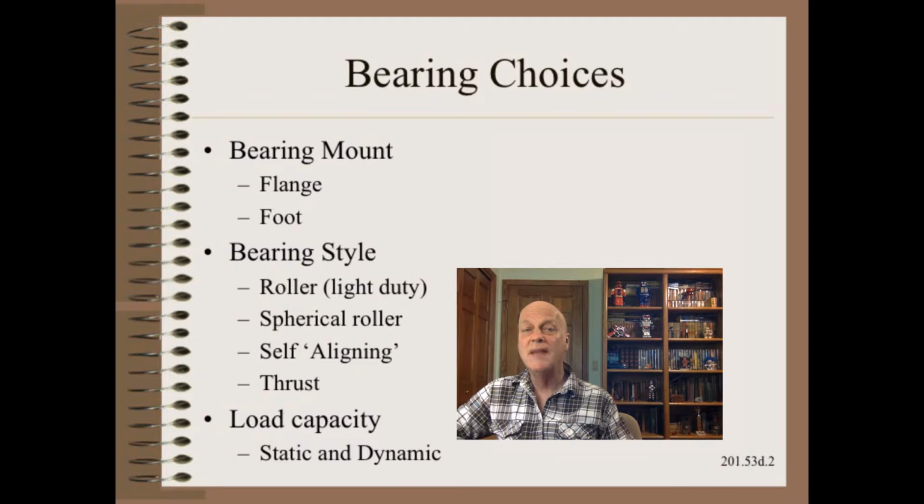By loads, we mean both static and dynamic. Static loading is weight. It also includes setting rollers on the floor or frame, which can brinell the inner race due to impact. Dynamic loads include rotating weight plus vibration loads.